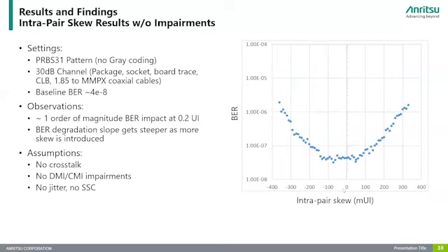So using this, we measured the skew tolerance of the DUT, the PCI-Gen 6 root complex. At 0 milli skew, the BER is E-8 or something, and at plus minus 100 milli there is almost no difference in the BER.